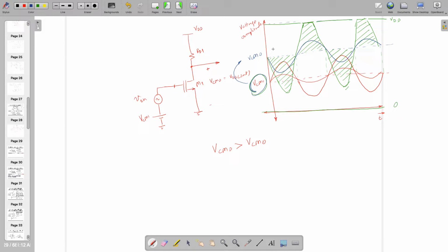In the case of PMOS, it will be different, where you will see the saturation at the ground side. So you must have experienced the same thing when you did the experiment on the common emitter amplifier, where there is some resistive load and your output reaching here. Most of the time it's on the positive side, and it's creating lots of problems for you. So in that case you reduced the input amplitude just to find out the exact value of gain, right? Because it becomes large signal. You should not give a large signal value of the input signal.